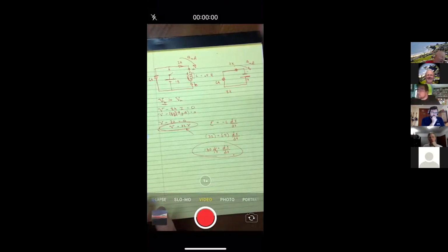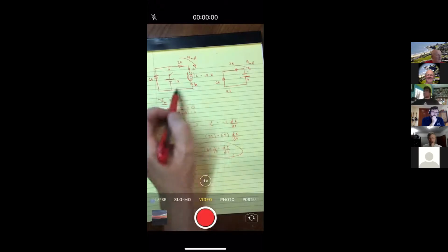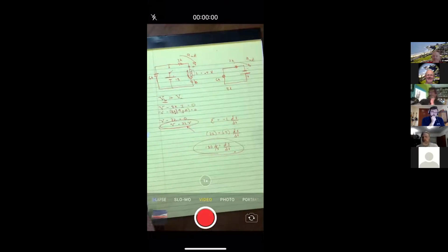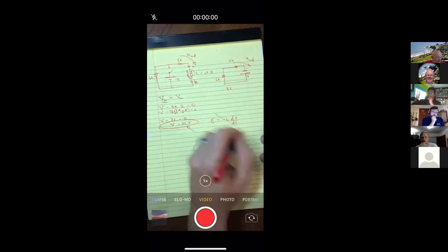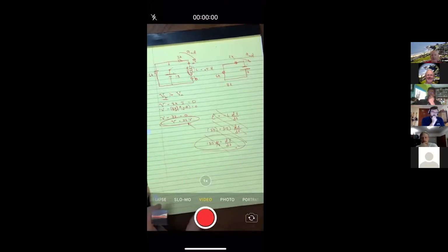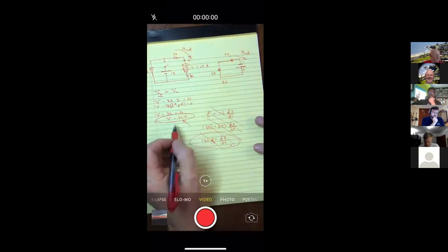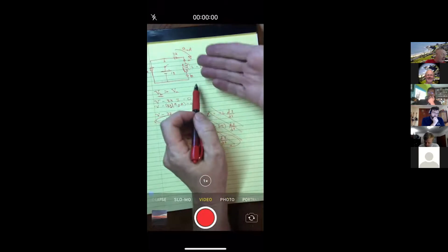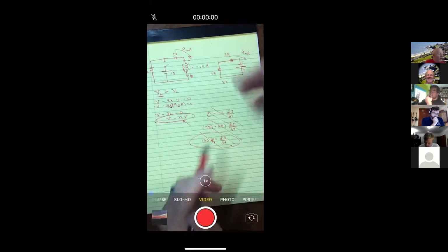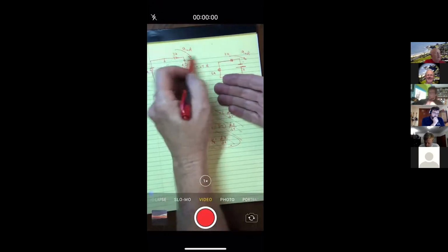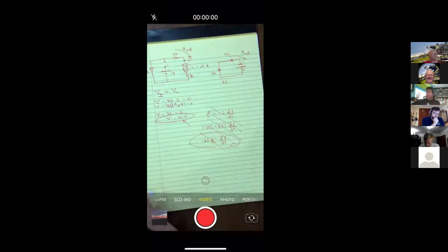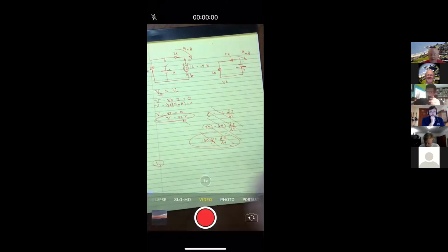But it will take a while, albeit a fraction of a second, before the current completely goes away in this inductor. And that was for free. So let me cross it out because I don't think they ask at what rate is the current now decreasing. They just ask for the voltage that would be created on the inductor, and I treated it as a motor that would then keep the current going around at this 9 milliamps. Okay, so with that in mind, I probably should go to part B of this problem.